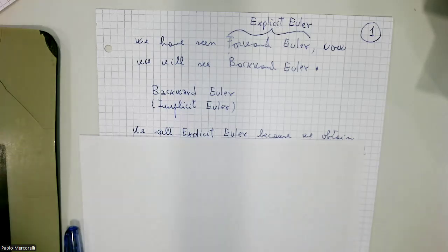Because as I told you, the discretization is an extremely important part of the controller, as we have seen today, but you can imagine also of the observer, because an observer is a controlled system. We have a feedback in the observer. You remember, Vincent? We have seen that the sample time T plays a fundamental role. And this means the method I use to approximate or describe the model is extremely important in the controller and in the observer.